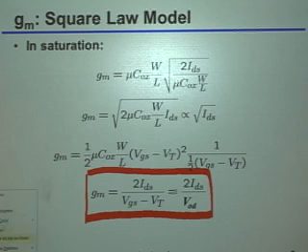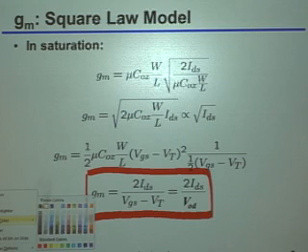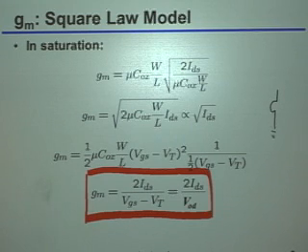So what you said was that typically that VDSAT was the minimum voltage you need in order to make sure the device was still in saturation, right? So if we looked at, let's say, a simple amplifier, and let me just abstract away the load as just being a current source, just have an NMOS device with an input here and an output over here, right?